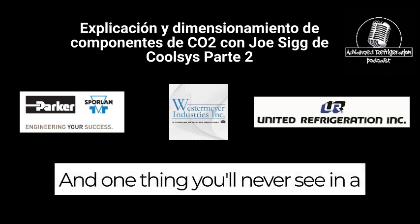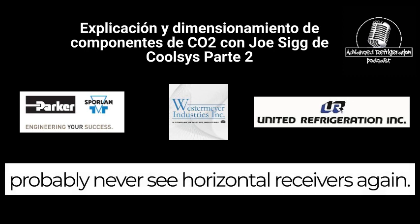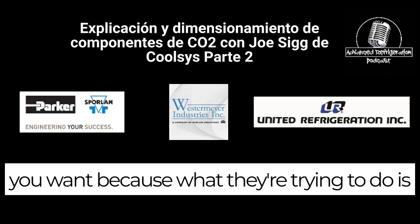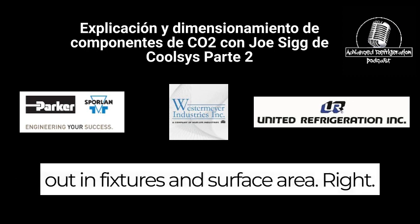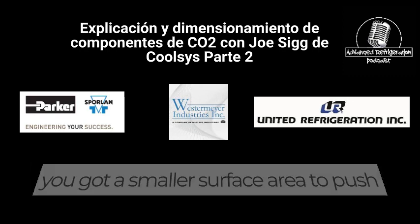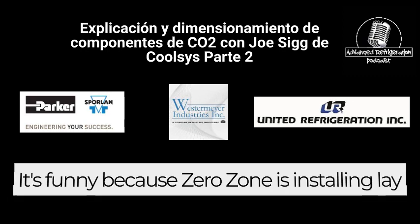And one thing you'll probably never see in a CO2 system again is horizontal receivers or horizontal flash tanks. They're all vertical because what they're trying to do is maintain a solid column of liquid out to the fixtures. If the receiver or the flash tank is standing up, you've got a smaller surface area to push up than you would with a horizontal.